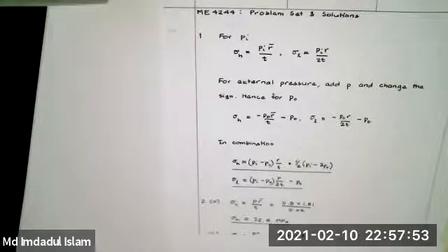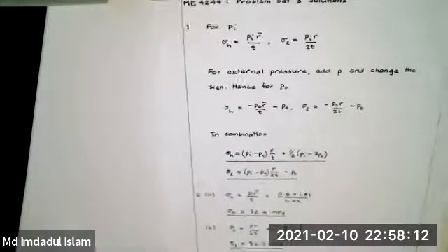The thickness was 20 millimeters, or 0.02 meters. Half of that is 0.01, so that's where the 1.81 comes from. There's no mistake there. And this is divided by 0.2. That gets you a hoop stress of 32.4 megapascals. You apply this formula, and you get a longitudinal stress of 36, about half. In this case, the thickness is pretty small, so Shigley's formula doesn't make much difference. That's not always true in practice.